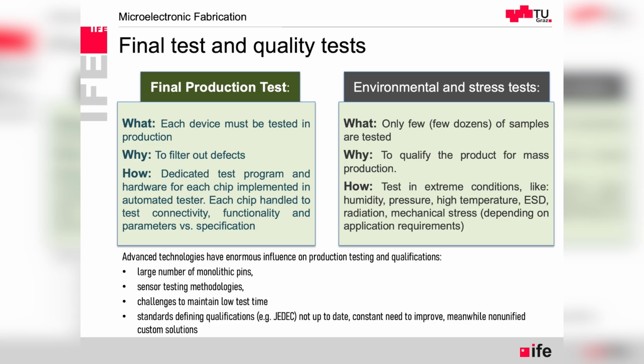considerations. For integrated solutions, including sensors, it's not only electrical testing anymore, because there is some interaction between the electrical and, for example, temperature, pressure, optical of different wavelengths, timing. So these kinds of things we want to have tested for every single chip. And so test engineers have lots of new challenges related to that. At the same time, we want to keep the test time low, because test time is one of the main factors of how much the chip is going to cost.